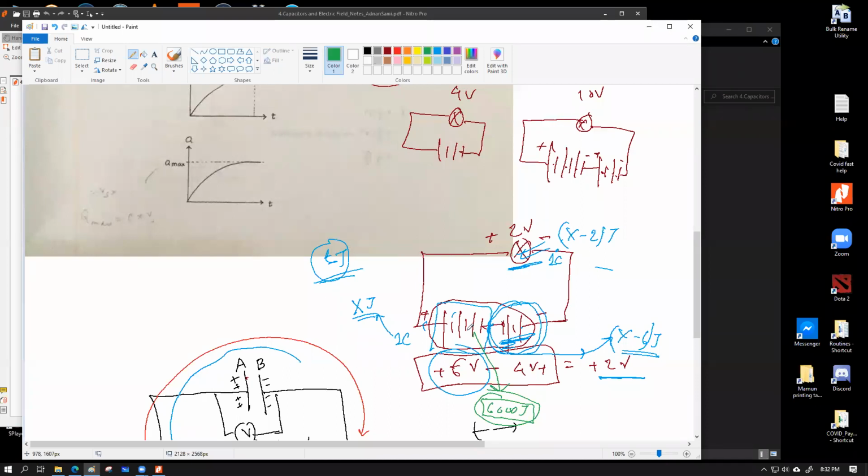That can vary from design to design, but we necessarily cannot extract 100% of the chemical energy that is introduced into a battery at any level. If we want to do that, we have to devise an adaptive system that adapts as the battery's voltage falls and can still drain energy out of it. With that, we could utilize the whole 6000 joule of energy in the battery. It's not impossible to design, but it's not very practical.